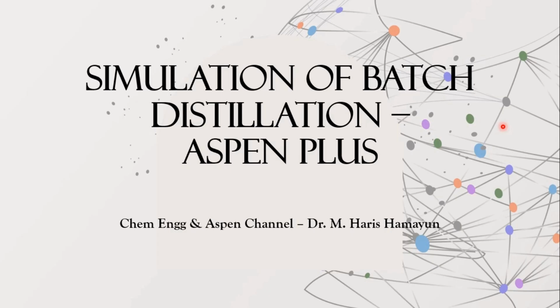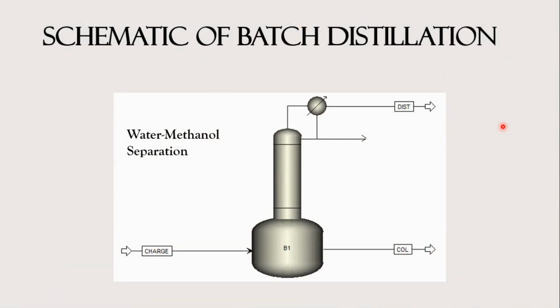In this tutorial, we will simulate the separation of a water-methanol mixture using a batch distillation column and analyze important results such as the temperature profile in the column, the composition of the receiver with time, and the composition changes inside the pot. This V1 represents the pot, this is the receiver part, this is the column, and this COL represents the contents inside the pot. So if you want to understand how batch distillation behaves dynamically in Aspen Plus, make sure to watch this video till the end.